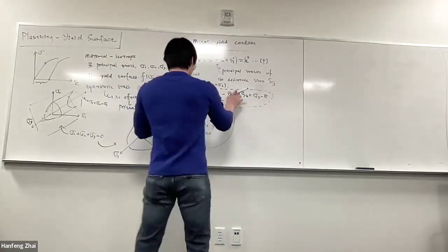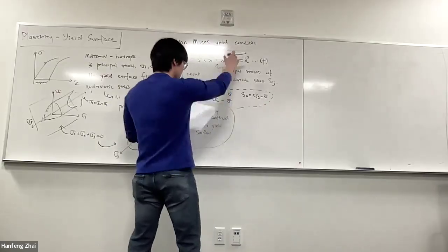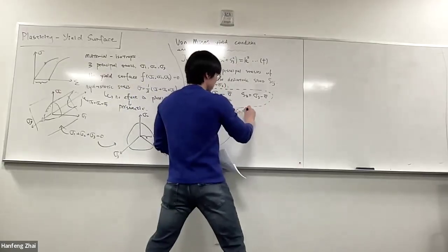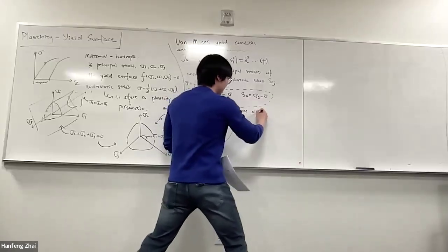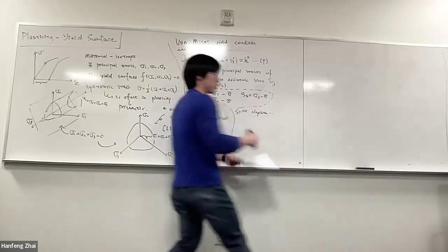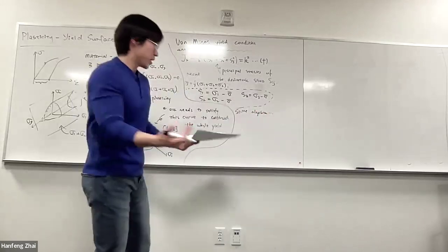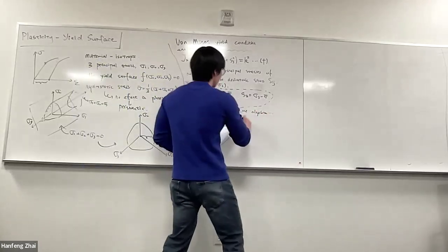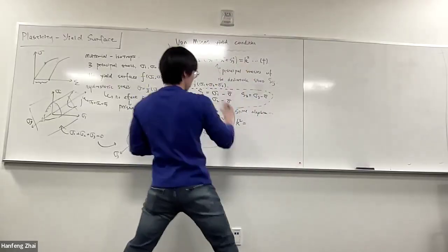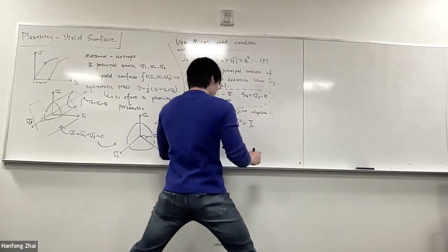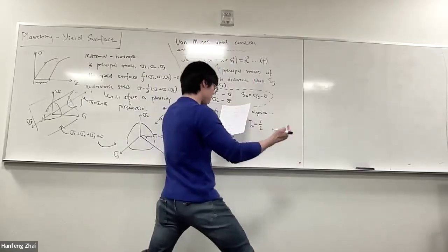So we use this formula, we substitute back into this equation, then my favorite term that I like to use in public sessions and lectures, we do some algebra, right? For efficiency to deliver the main message, I'm going to skip the algebra. So what is the conclusion? k squared, the value we defined here, by definition equals J2, which is 1/2 the three principal deviatoric stress components.